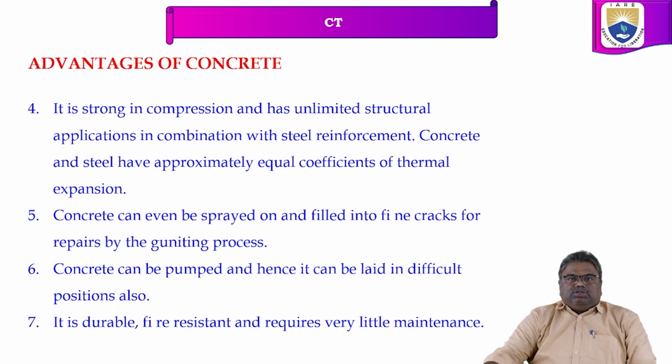The fifth one: concrete can even be sprayed and filled into fine cracks, and repairs can be done by the guniting process. We can spray the concrete to repair the finest cracks. The sixth one: concrete can be pumped, and hence it can be laid in difficult positions also.